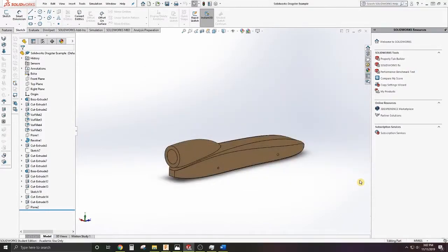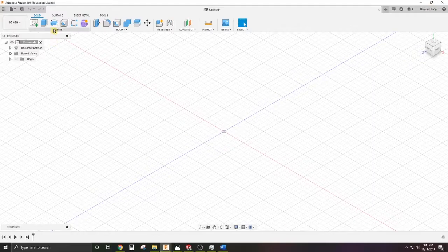That step file is a language that pretty much all CAD software understands. It's been around for many years. Inventor, Fusion, SolidWorks, they all can deal in step files, and it pretty much transfers back and forth. But when I do open that file in Fusion, I will lose the ability to edit each one of these features independently. So that is a disadvantage. If I would model the dragster in Fusion entirely, I would have that option to modify those things here. But those are just some advantages and disadvantages of modeling and where you create the geometry. But Fusion is great regardless for creating toolpaths and geometry.